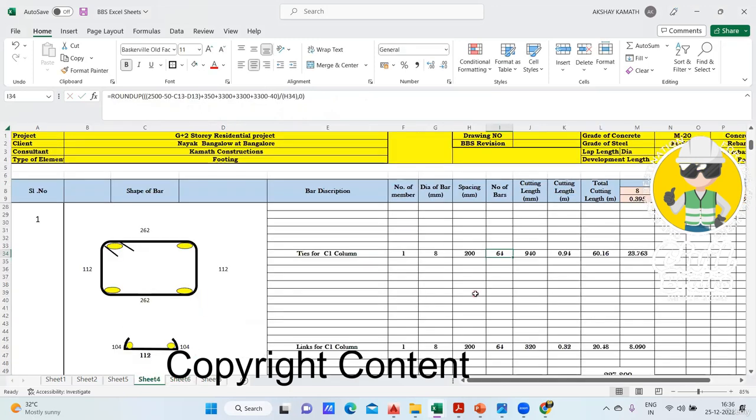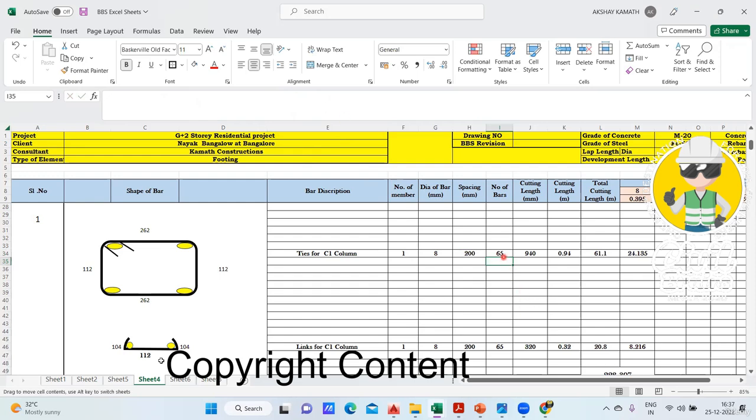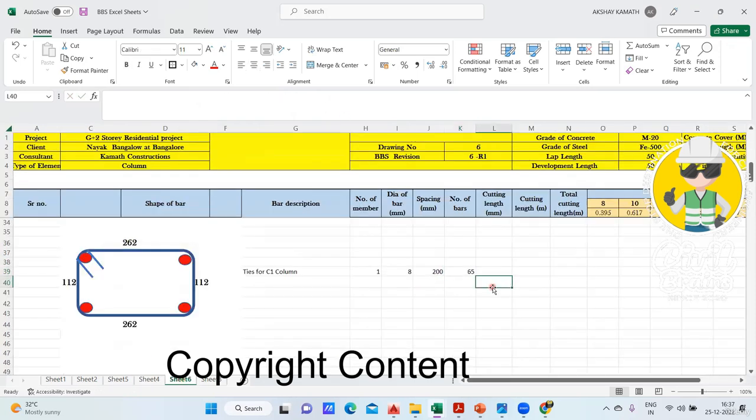Here it was 64, no? Why is it 64 here? So h by 200 was the spacing. Okay, plus one I didn't add here. One mistake I did, because whenever you're taking this, I should have done plus one. Now it will be correct. Why plus one? For the very same reason. It's lateral ties, no? By doing this, we'll find the spacing. That is why plus one we should have done. Exactly. See, 65. Here also I got 65. It's okay. Sometimes when you do BBS, slight mistakes happen here and there. Not an issue. In one, nothing is going to happen.